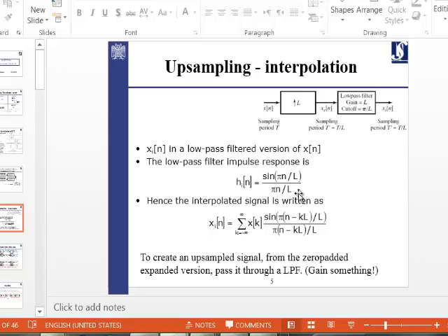For upsampling, it is the other way around. The spectrum of the signal is compressed, so we have no danger of overlapping. The only thing that happens is that you lose resolution in the frequency, but not the information itself. Now, I mentioned already that upsampling and downsampling by themselves maybe do not mean a lot, but they are used for filtering in filter bank implementations.